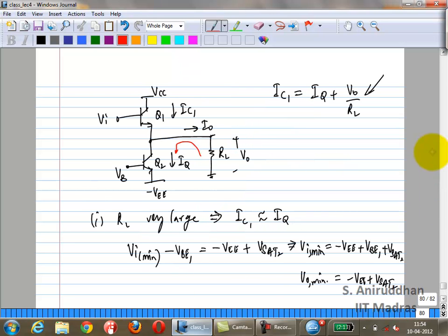Can you have Vi equal to VO equal to 0 here? There is always, okay, so close to the origin, the transistor is going to at least have a bias current, IQ, through it, correct? So between Vi and Vo, you always have a VBE drop, correct?